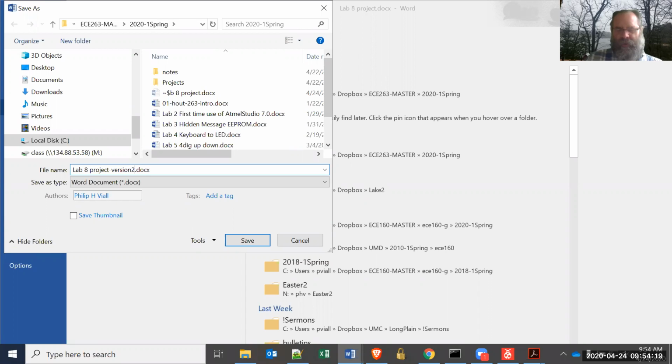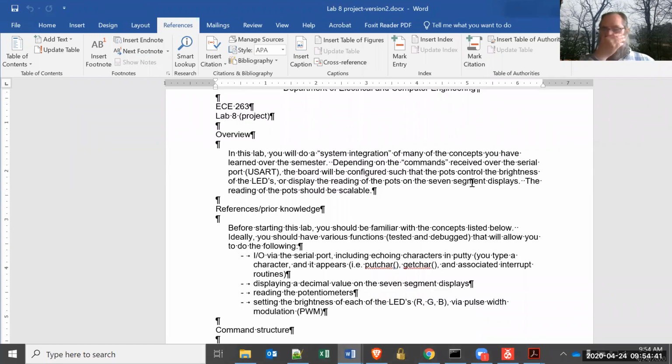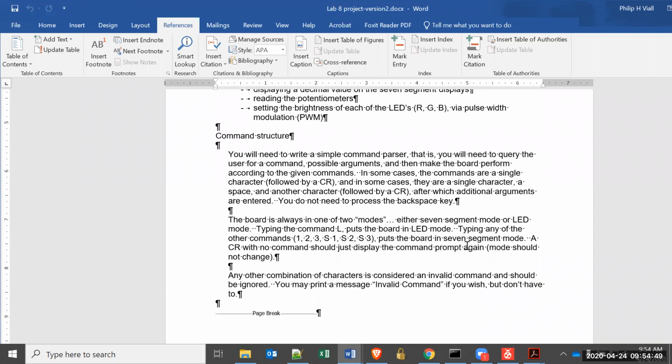But in order to display anything on the 7-segment displays, you need to be constantly refreshing them. Oh, I know. Maybe you could turn off the receive, transmit, and interrupt flags when you're setting that up for like 30 seconds, and then do the refreshing on the 7-seg with the potentiometer.